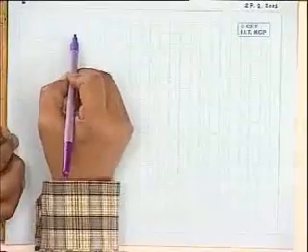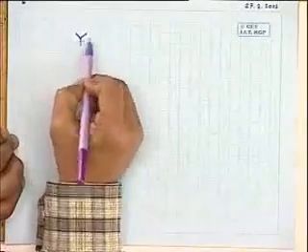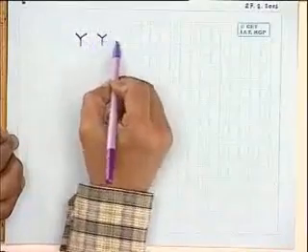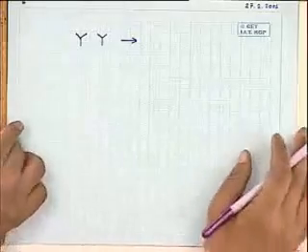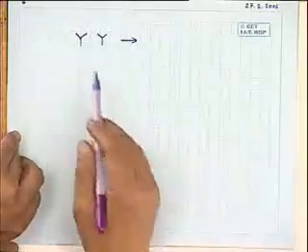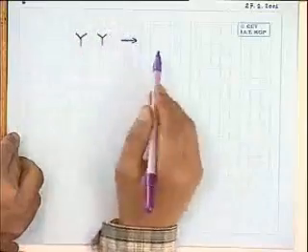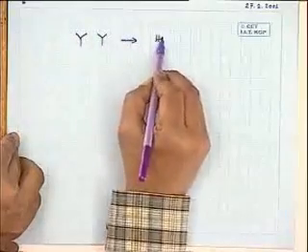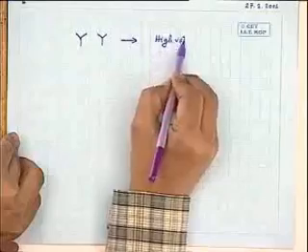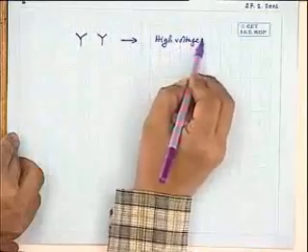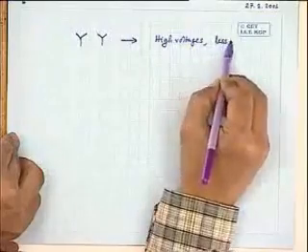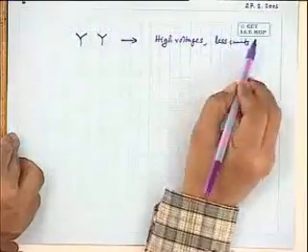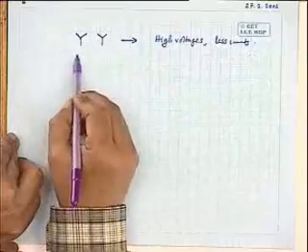Therefore, remember that there are several connections now available in a transformer, of which star-star connections, when to use. I will just briefly tell star-star connection when to use. Generally, it is to be used for relatively high voltage ratings on both the sides. High voltages, but less currents, less currents.